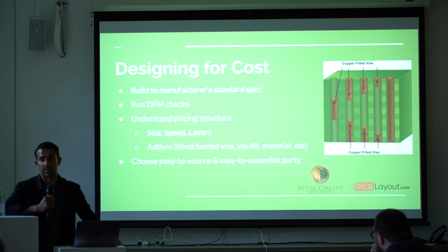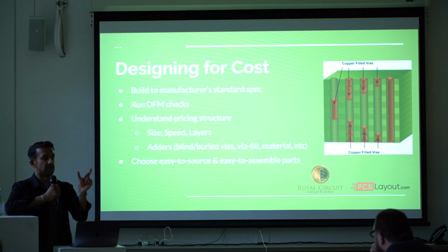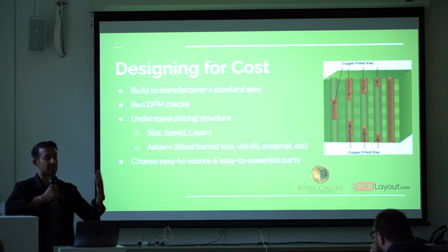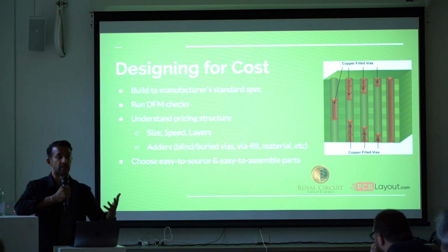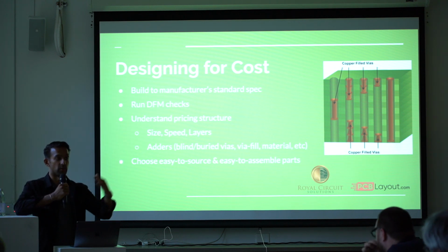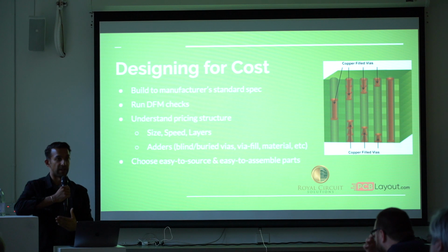Okay, the size is relevant because we do not build boards individually. Like you have a small 3x3 board, it doesn't work that way. We actually have to put that on an entire panel. And if we're going to run an entire panel for you, we charge you for the entire panel. The good news about that for the engineer, though, is if you want 1 or if you want 100, if they all fit on the same panel, the price theoretically should really be the same